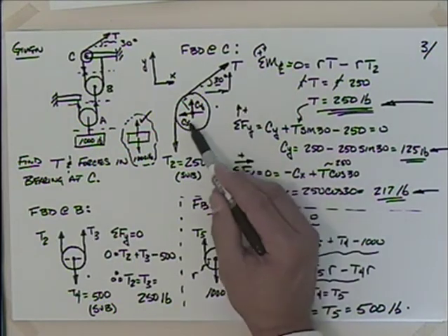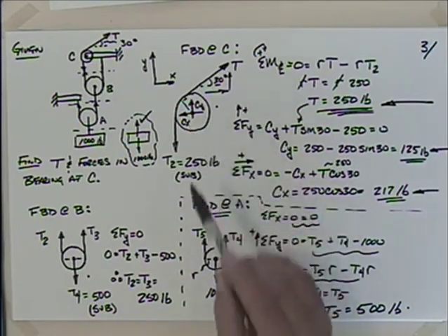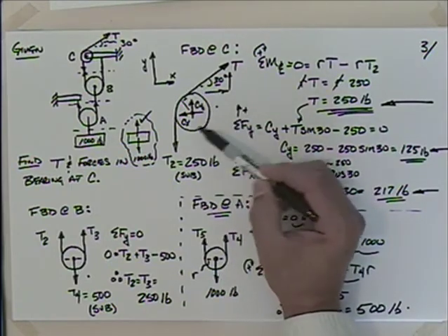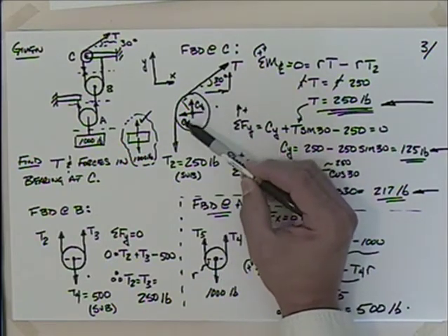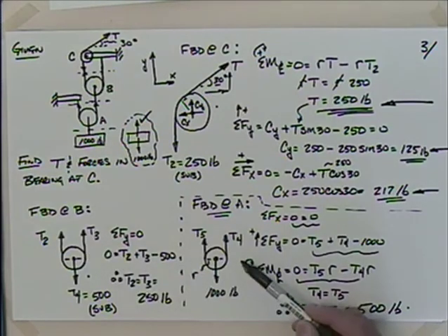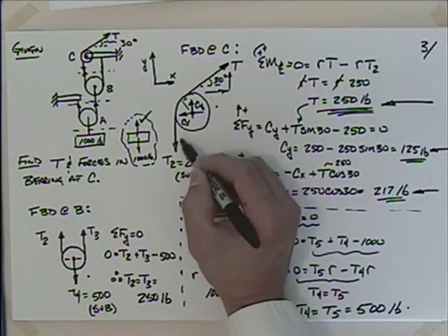guess, because these numbers could be plus or minus infinity, right? So you'd have virtually no chance of guessing it right. So don't guess. When you get to something where you don't have enough information, don't guess. Go draw another free body diagram, and then start to work your way back with the information that you found. Now, another thing you might wonder, well, how did you put this tension in this way?